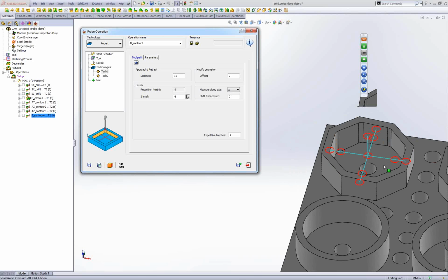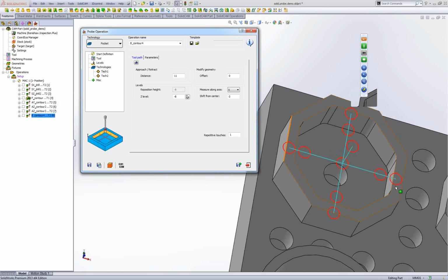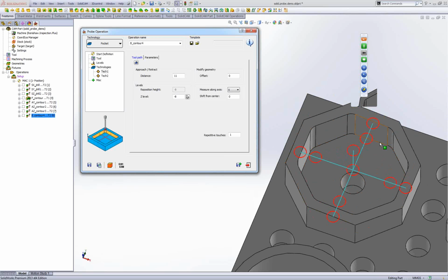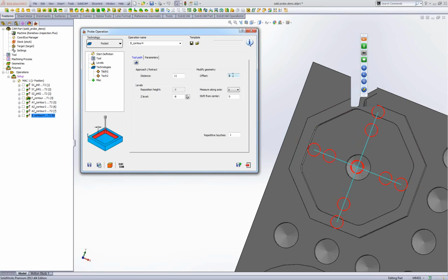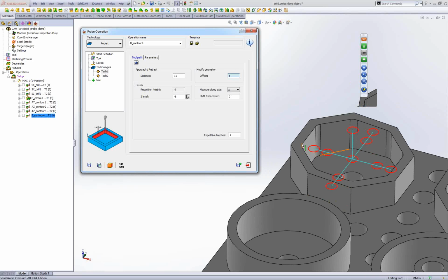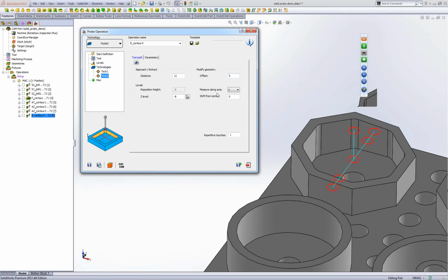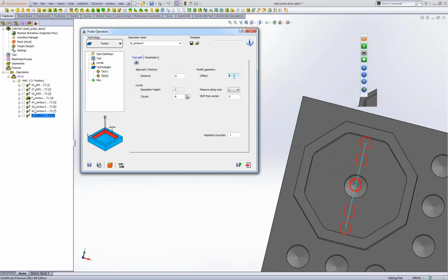Measure this internal. Now I don't want to define another geometry. I can define the internal geometry, yes, but it's easier for me to use the offset here. The width of the wall is 5 millimeters, so if I use here 5 millimeters offset, I can use the same geometry. Save, and for technology number 2 also in y-axis, use the offset, save and calculate.